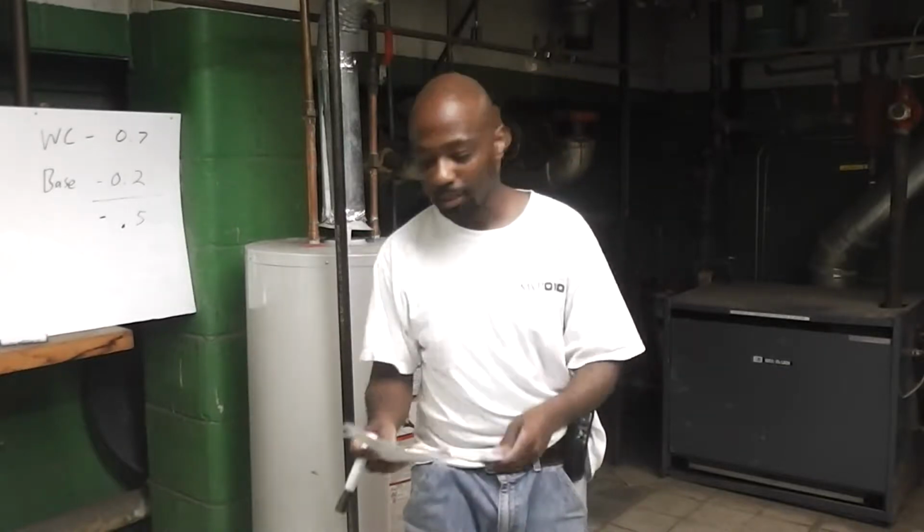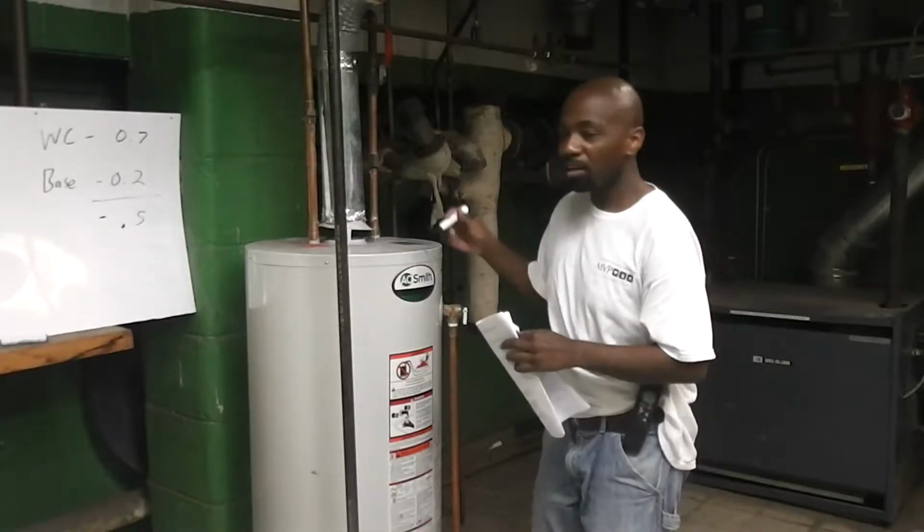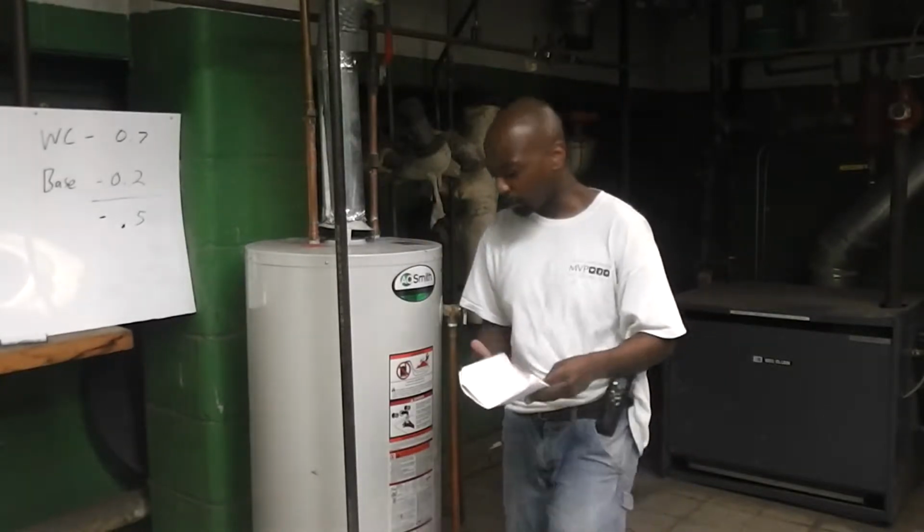Let's continue the test. The next part of the test is spillage. When I turn this on, I want to see if those flue gases are actually coming out.